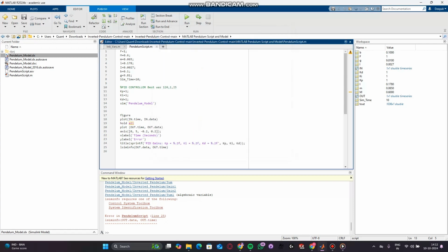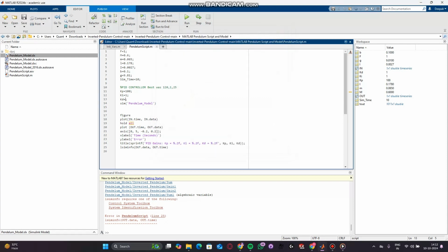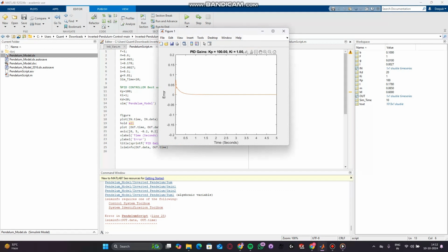Then what I do is I increase kp a lot. When I increase kp a lot, I get an oscillatory graph. If you remember, I spoke about this before. This is an oscillatory graph, and it is stabilizing, but very late, because my ki and kd values are non-zero. It's still 1, so that's why it's stabilizing very late. The way I discussed to fix this was to increase my kd value. So let me try doing that. I increase my kd value to say 20 times of it. See, now it's not oscillating; it's just stabilizing pretty fast.